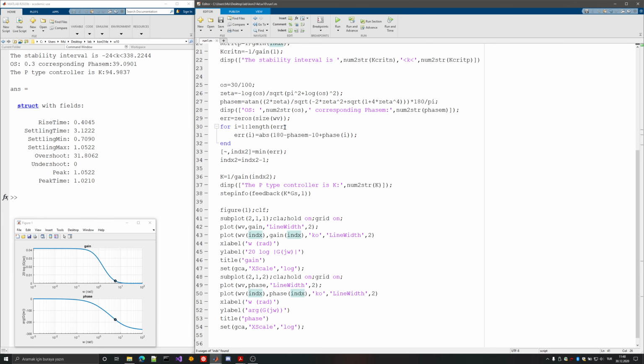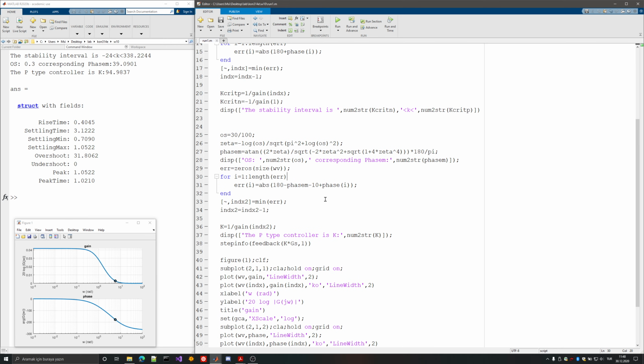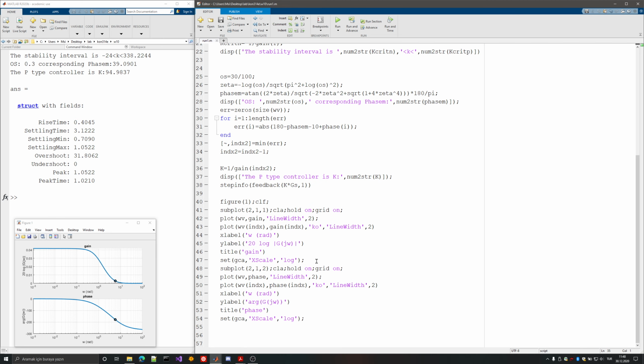And as I've told you, the point where this is working very well is the point where the phase margin is very low, so you are in the danger zone, so this helps you. And that's also the reason why I have added 10 degrees, because it works better in the danger zone. So being a little bit even more conservative is even a better idea. If this formula would have been working better for zeta equals 1 or the vicinity of that value, then I wouldn't need to add this 10 degrees safety margin. It depends, by the way. You can use 5, you can use 12. Those are the common intervals.